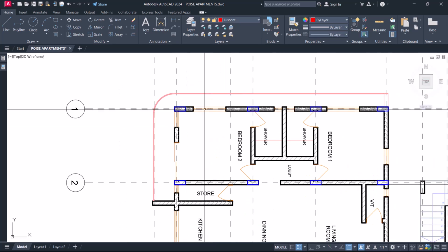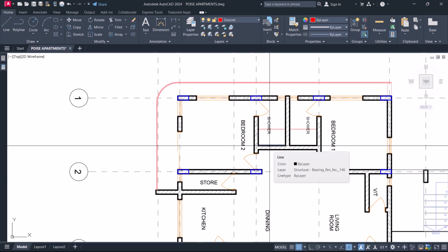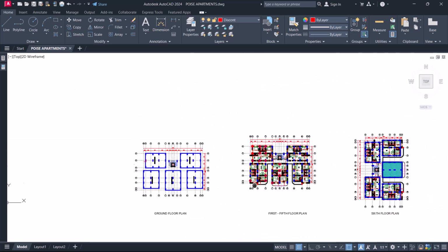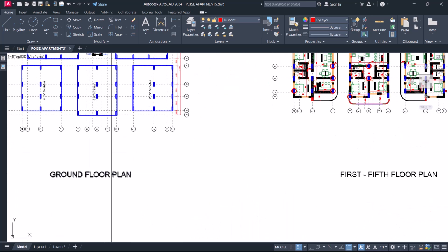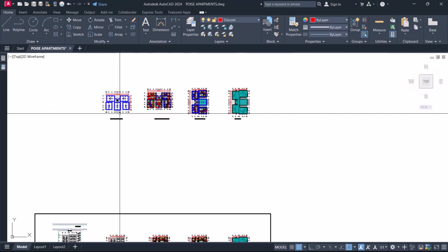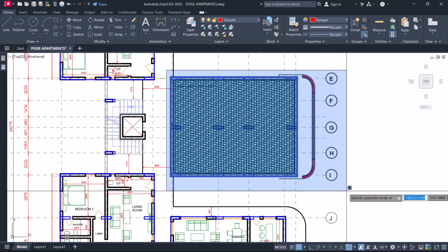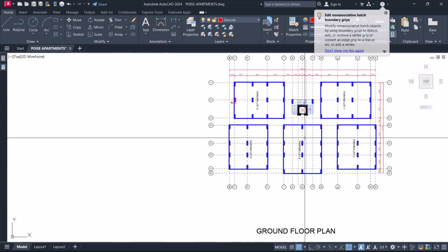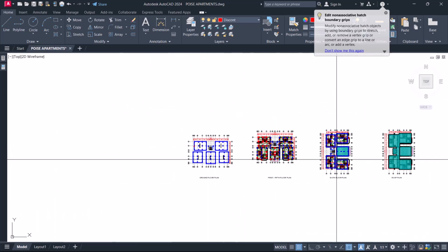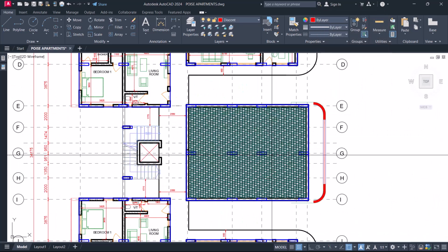The next thing is, since we are sure that this does not interfere with windows, doors, or entrances, we can go ahead and erase our windows, then we'll erase our doors as well, because these columns can go all the way from the ground floor up to the 6th floor, with the exception of the other parking lots area 3, where there is a roof at the sixth floor.